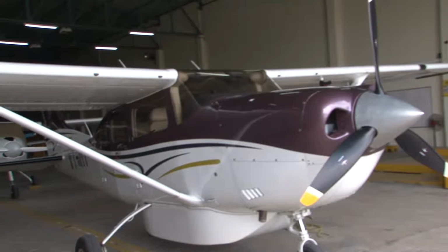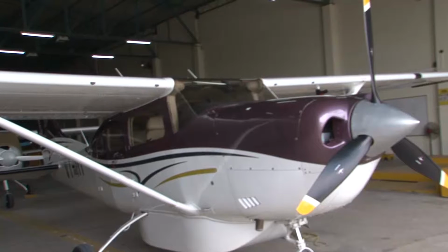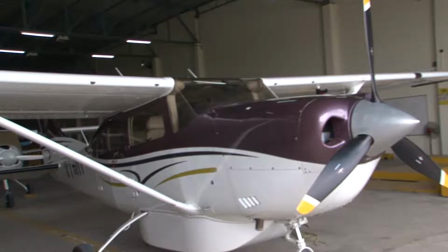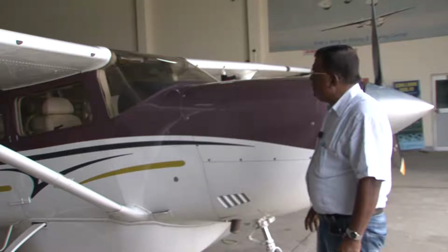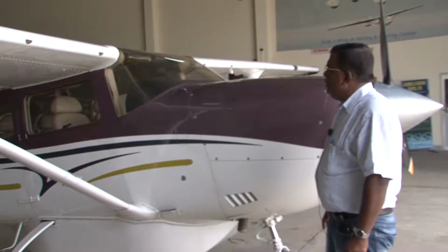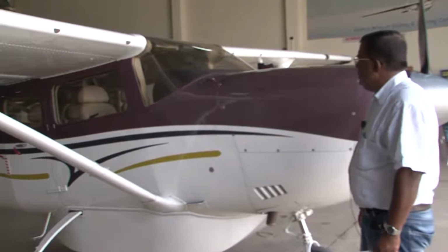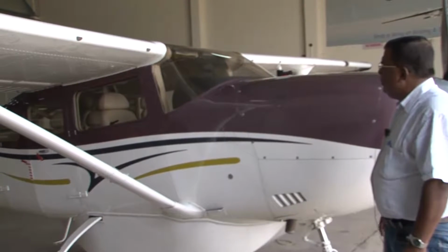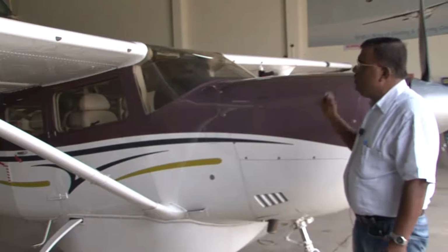Once you know these basic dimensions, you can easily start conceptualizing a sketch. Then you add the laws of physics and make the airplane the way you want it to fly. See, when I am trying to draw a sketch in my mind of an airplane, it is not only important that you know how much will be the wing area or the fuselage area, fuselage volume, but you also should know how they are located relative to each other.